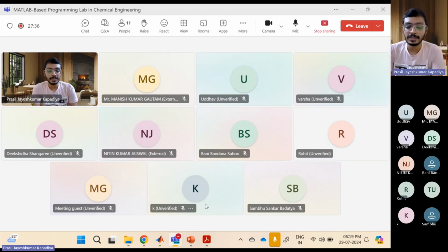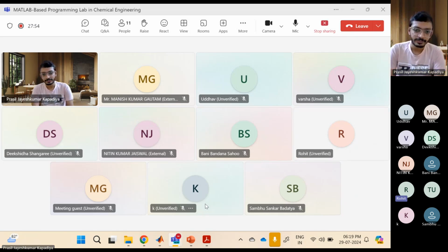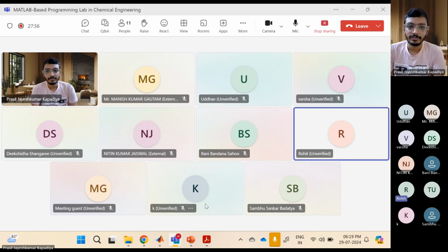Let's say I'm just giving you a condition. Because of compressing my gas, something is converted into liquid. Is it feasible for my compressor if something like that happened? No, not feasible. What will happen? The compressor shaft will be damaged.